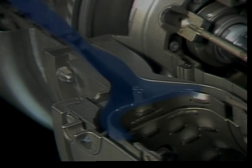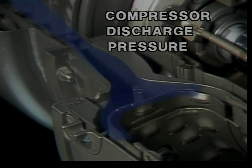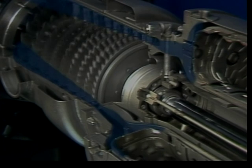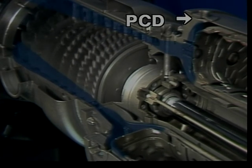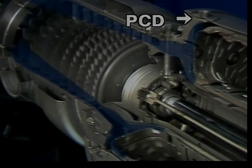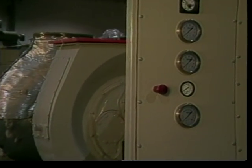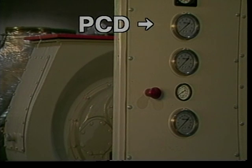Since this pressure is most important in monitoring engine performance, it's given a special name, the compressor discharge pressure, or abbreviated in engineering terms, PCD. On the Saturn engine, PCD is measured at the bleed air boss on top of the combustor dome. A PCD gauge is mounted on the engine gauge panel.